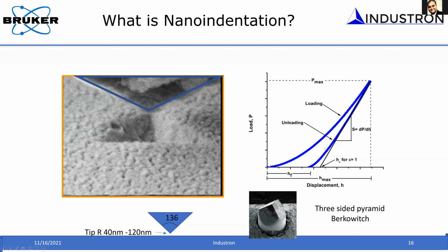Okay, so for example, if the material is highly plastic, you will see this hysteresis is very high. For example, if you load and unload, it will unload with a vertical drop. And if the material is highly elastic, I mentioned that it will have only elastic deformation. So in between, you will see this variation of the hysteresis.